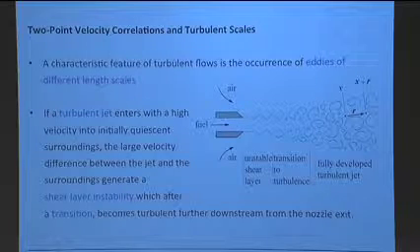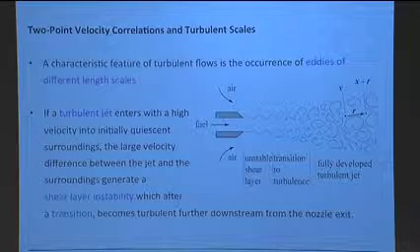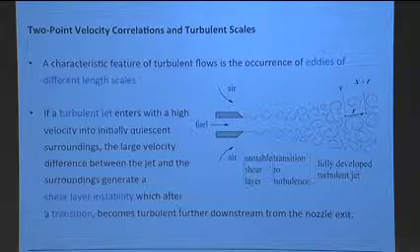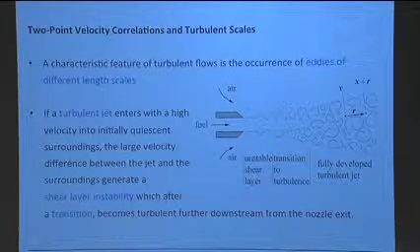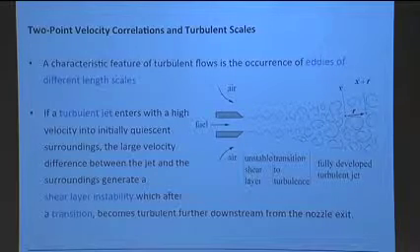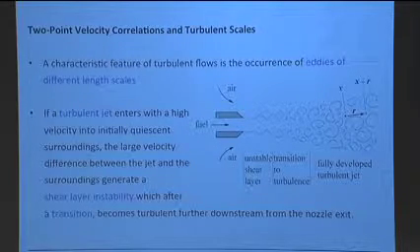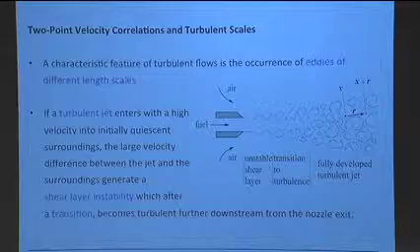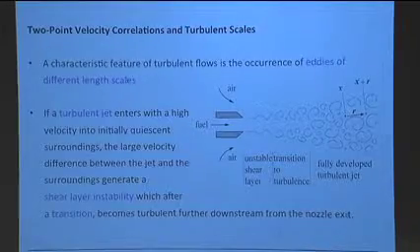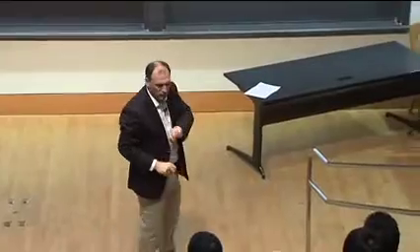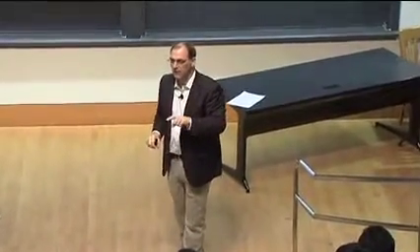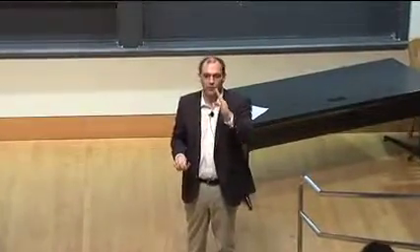And then you have different eddies and they interact with each other. And by doing that, they break up into smaller eddies. Okay? And these smaller eddies are a part of the larger eddies. You have a big eddy that goes like this, and in the big eddy you have smaller eddies that do something else. And then these smaller eddies interact with each other, they form yet smaller eddies, and so on. By going from large to small, what you do is essentially you increase the local gradients.